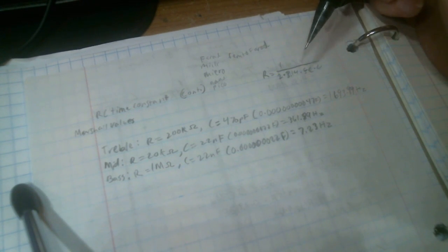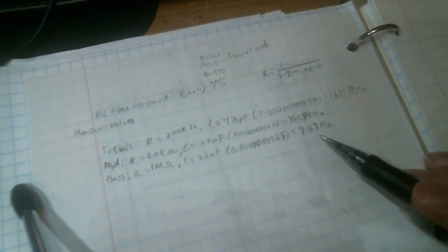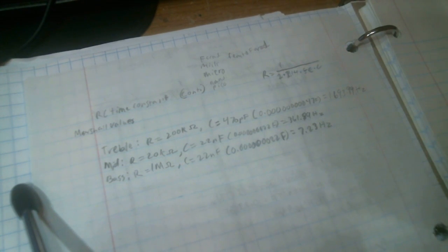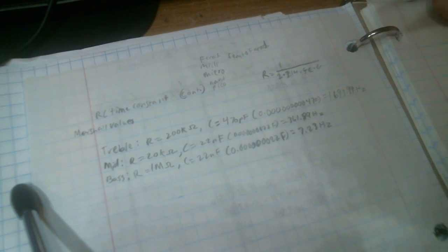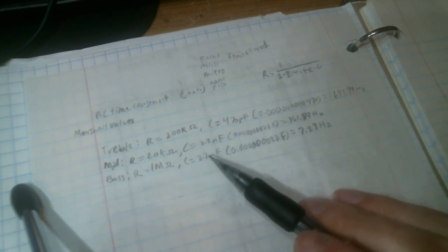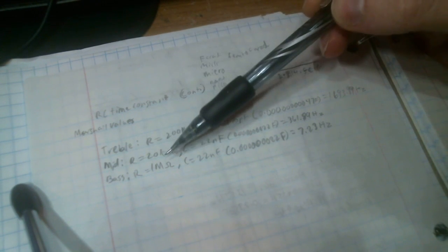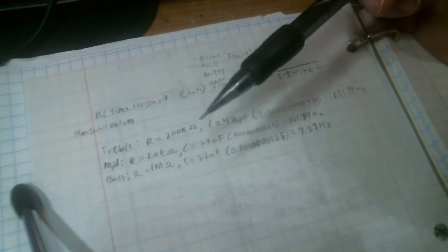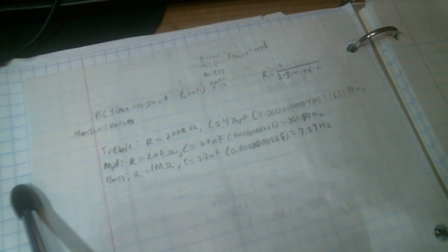Now this is only finding the beginning of the range. So like bass, it's at 7 hertz. And this is a guitar amp, it's not a bass amp. So if it maxed at 7 hertz, it would be useless. The only thing you'd be taking out is like some muddiness, and it wouldn't even really be noticeable. But to find the max of this, once you have everything here, your capacitance can be variable. I don't have a variable capacitor, but I do have many variable resistors. More than I showed you even. I should be getting more though. I don't have as many values as I would like.